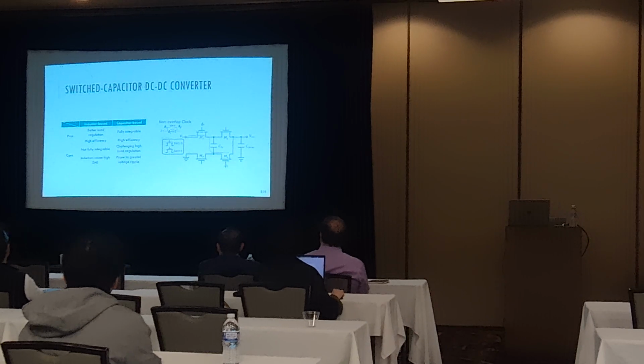So that's the schematic of our capacitor-based IVR, where we use 4 IGZO transistors, 2 of them in depletion mode and 2 of them in enhancement mode. Because we don't have a P-type device, we need to use this N-type to simulate what P does. And then we also need 2 capacitors.